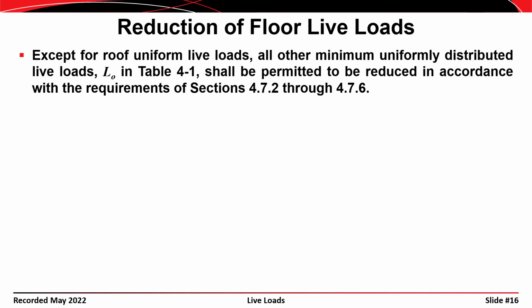But consider a column that supports several levels of flooring and might support a tributary area that is in the thousands of square feet. The odds of all of that tributary area being loaded to its full design load is much lower than the first case. So in that case, where the tributary area is higher, we're permitted to design for a reduced live load.